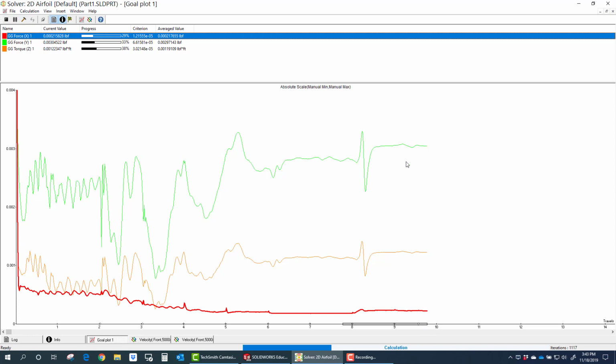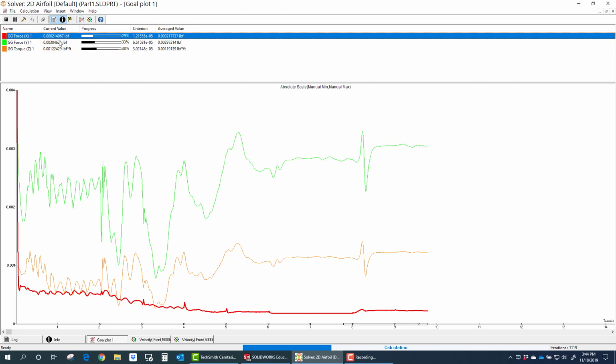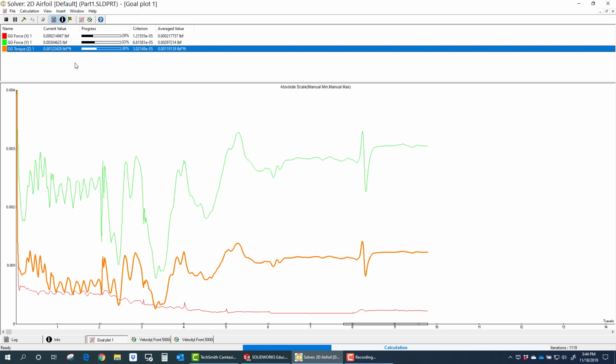That's nice in a pinch if you want to do a quick refinement, but probably would have been better off to let it hit 10. But still, you notice even though the number of elements went up, very little change happened in the solution. I'll let it run longer, but I'm pretty convinced that this solution is converged, and these are the actual values that we're going to get for the unknowns.